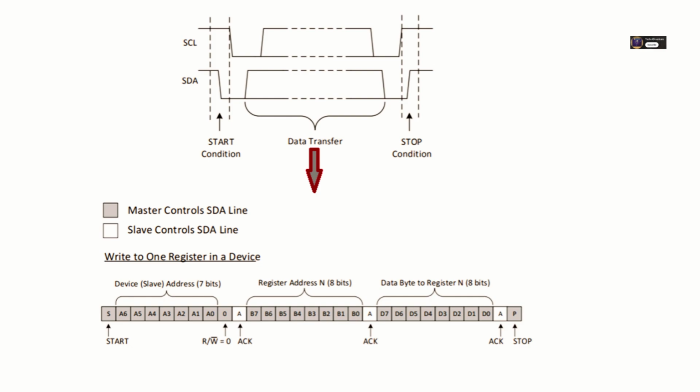And then the addressed slave has to respond. This is the ACK/NACK part. Sounds important for knowing if the communication is working. Absolutely vital. The acknowledge mechanism provides handshake and flow control. After every single byte is transmitted, the address byte, any subsequent data bytes, the receiving device takes control of the SDA line for one extra clock pulse, the 9th clock pulse.